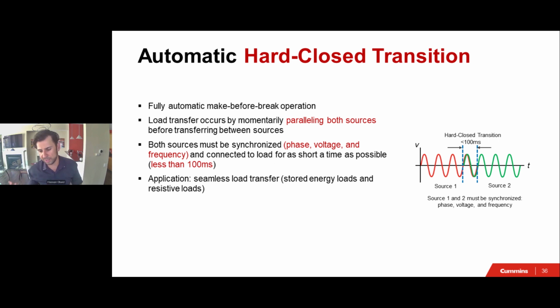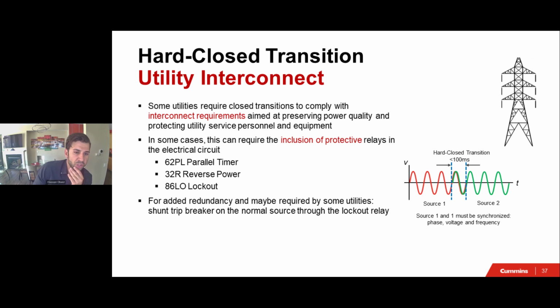And obviously you use this a lot if you're doing testing with load, or if the utility comes back and you're going from the generator to the utility. When you have close transition operation, you need to have an agreement with the utility. The utilities are not too thrilled about you specifying close transition. They really don't jump on that opportunity and say, yes, I'm going to help you with that right away. Usually they take their sweet time and you want to initiate this process at least 6 months in advance.